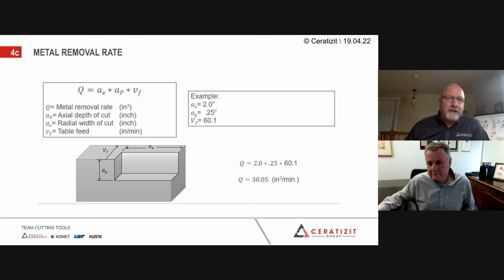And really, at the end of the day, it is about productivity, because the cost of tooling is maybe 3 to 5% of the total manufacturing cost. So what's really important is how quickly can you machine a part. So you're going to look at high feed milling systems as your roughers or your medium machine go-to type cutters. And then you're going to have to come back through and come in with some finishing cutters to, say, clean up the corners of the pockets and whatnot. So this is one of the main features of the high feed systems. Very high metal removal rates.